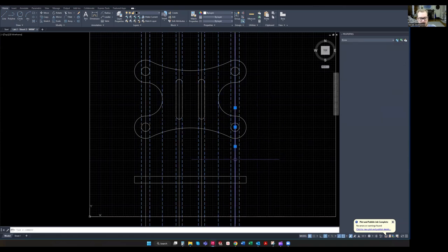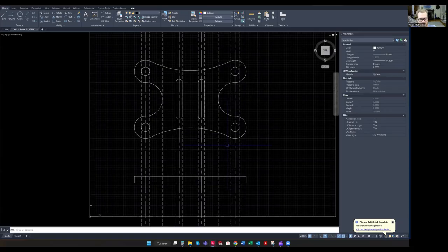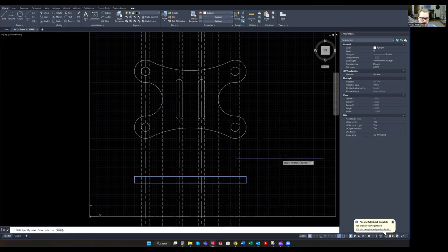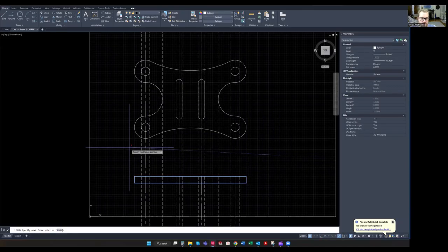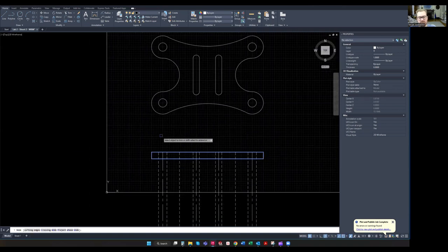Then select all the other lines, the lines that are still continuous, which are the center lines. Click on those and make those center 2 to differentiate between the 2 line types. Now, highlight this rectangle and type TR and click enter 1 time. Then just click, and let go, and then you move your cursor over here to the left, click again. And that's going to trim everything above this rectangle, and do the same thing below.